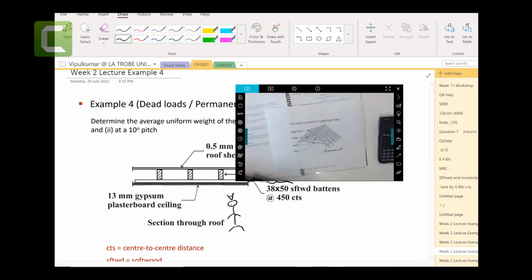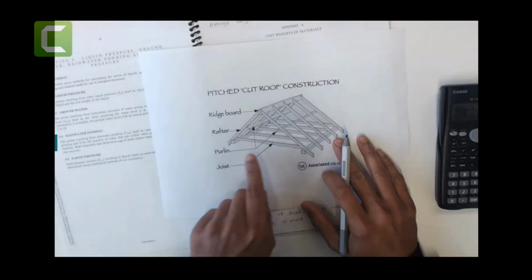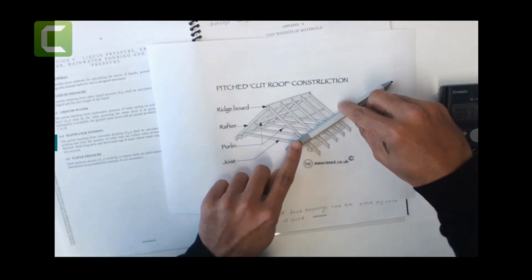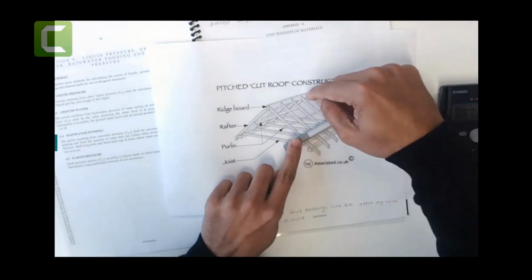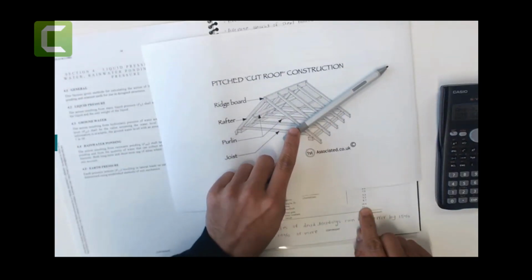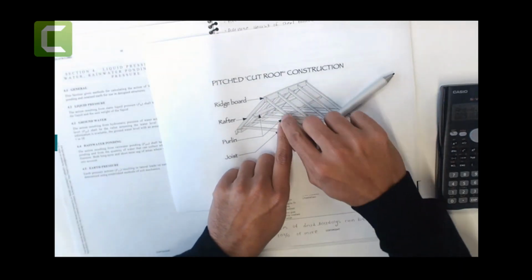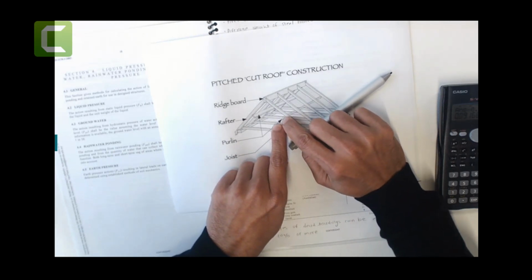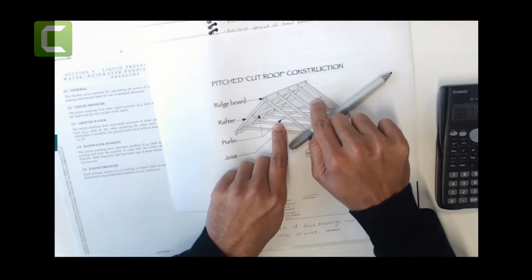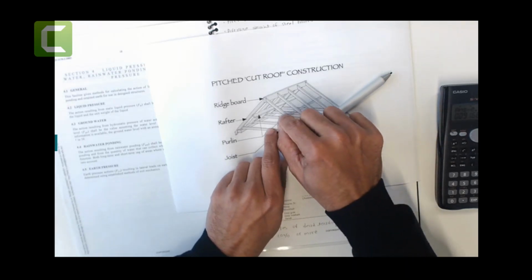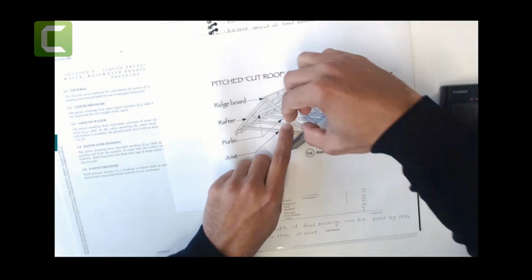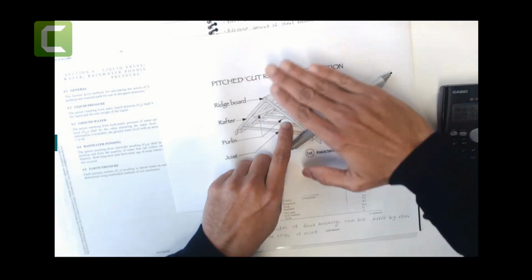First of all, this is a purlin. Look at this purlin, right? There is another purlin here, okay, another purlin here, 900. Now this purlin has a density of 11 kilonewton per meter cube, and it has a cross section area 50 by 150. So this will create the UDL load on the roof in that fashion. Then I want to calculate the pressures.